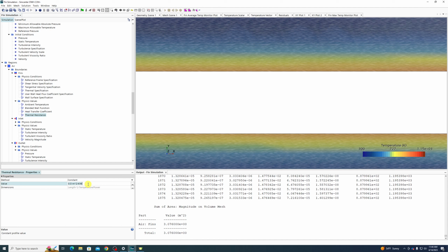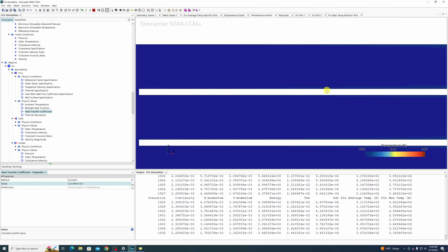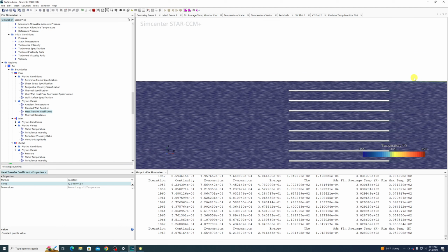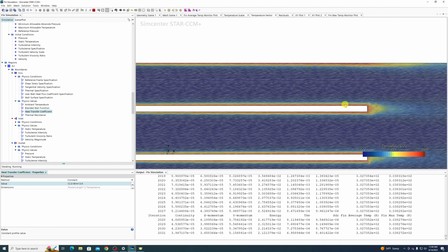And you know some value of insulation, so like, I don't know, 0.05, 0.1. I don't know how reasonable that number is, but let's assume that that's correct for a second. 120 degrees Fahrenheit, and it's natural convection, so it has a reasonably high heat transfer coefficient. We'll call it like 12. Well, it's obviously not going to be 1,000 degrees Celsius or anything silly like that. The temperature is working on bleeding its way out here. And we get a couple degree rise here.